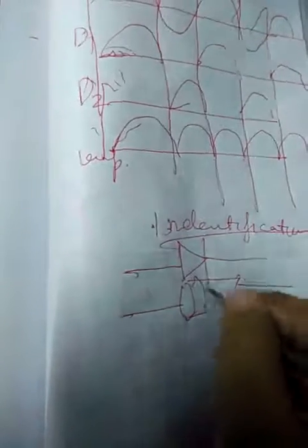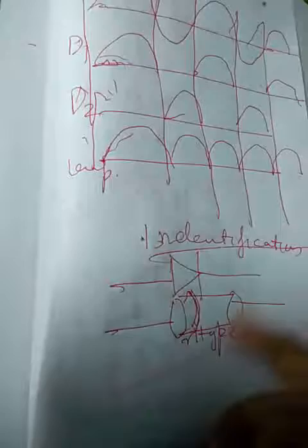When you go to the market to purchase a diode, how will you identify whether you have purchased a proper diode or not? We know the symbol of the diode and we used to teach the symbol only. But practically the diode looks cylindrical in shape and has a silver line at one end. When this silver line is attached, that indicates the N type. When you go to the shop, you see this is basically black in color and this is silver in form.